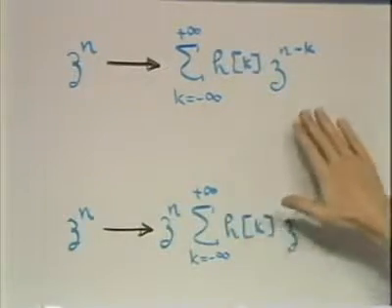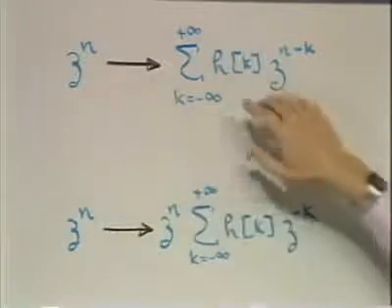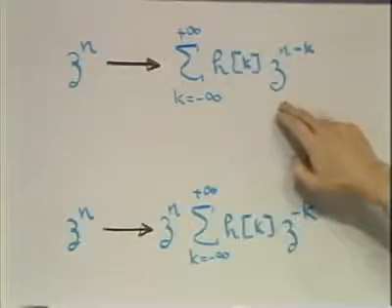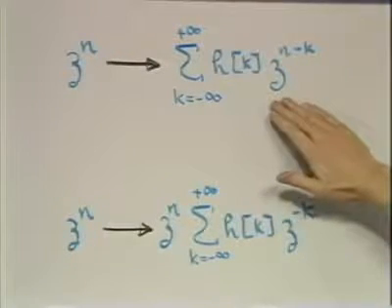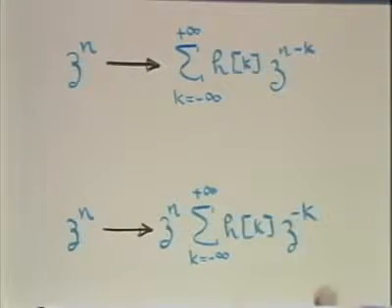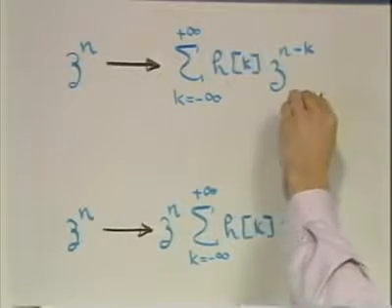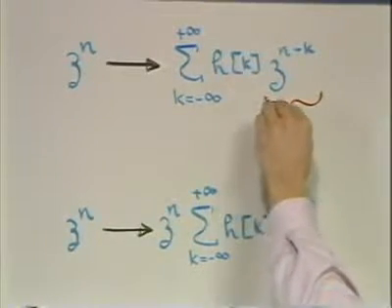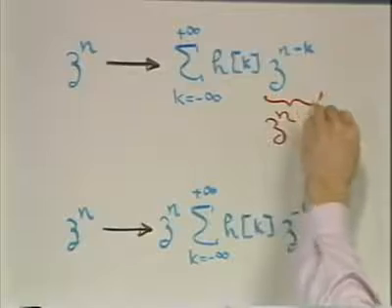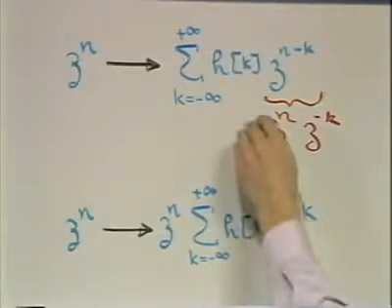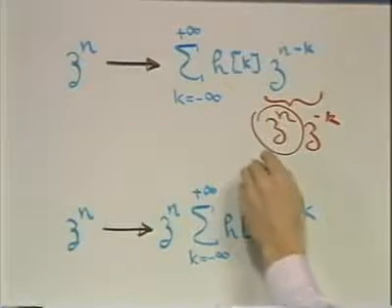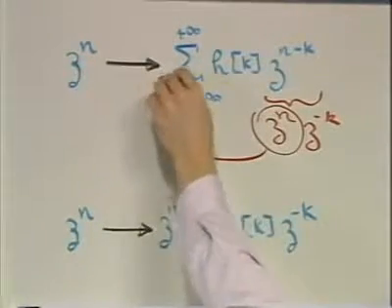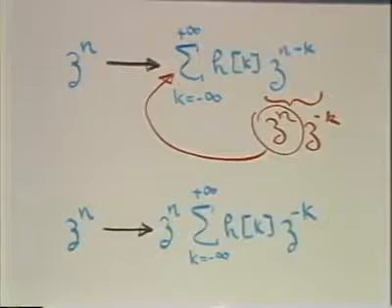So we can see that by substituting that into the convolution sum and recognizing, again, very strongly paralleling the continuous time argument, that we can rewrite this factor as z to the n, z to the minus k. And because it's a sum on k, and this term doesn't depend on k, we can take that term out.